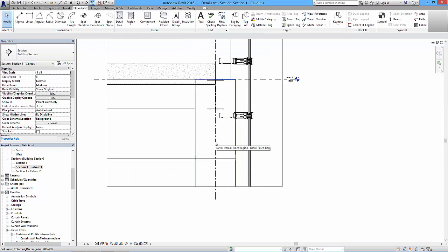Now we've got another instance whereby we want to put in the much more detailed suspended ceiling. It wouldn't just float in mid-air. It's going to have to be fixed by a load of brackets, and next time you walk into a building which has a suspended ceiling system, you can see parts of the detail. Just have a look at it. There's lots and lots of bits of track and cabling going on to hold the grid up, and the way it interacts with this curtain wall system is going to be crucial to our system as well.